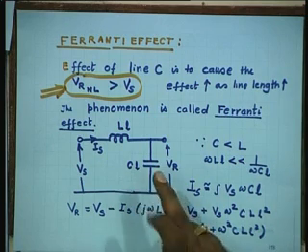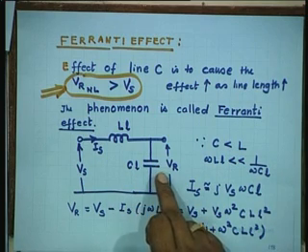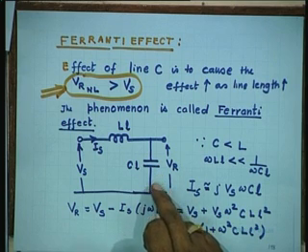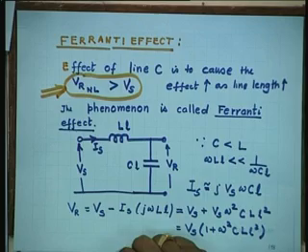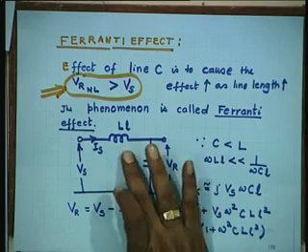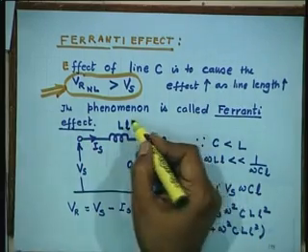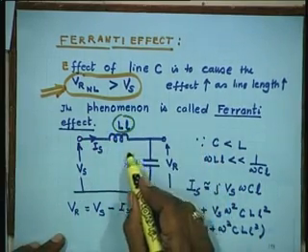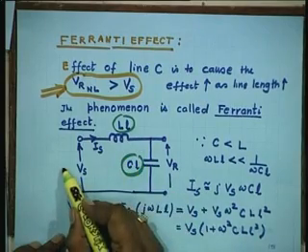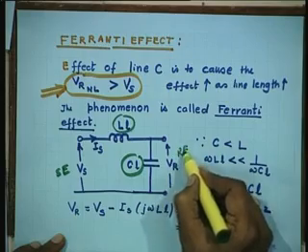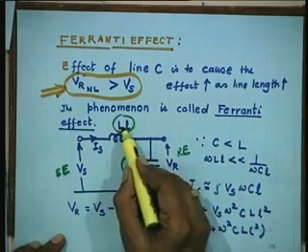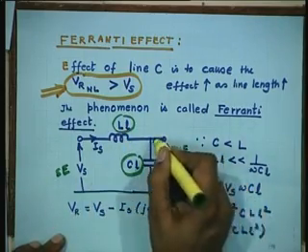Now, this is a very simple model. There is a capacitance, this is the very first model which we used before T and pi, right, the L model. So, here there is a capacitance at the end of the line, and there is an inductance, and L is the length of the line. So, total inductance is l into L, total capacitance is c into L. This is sending end and this is receiving end. This is VR, this is VS, this is IS and this is IR.